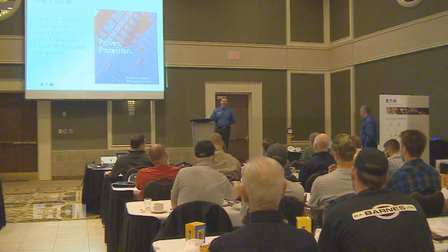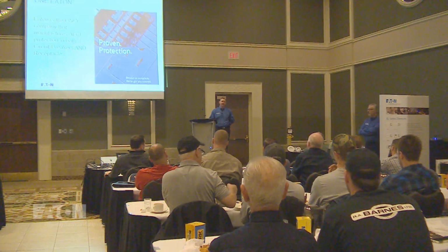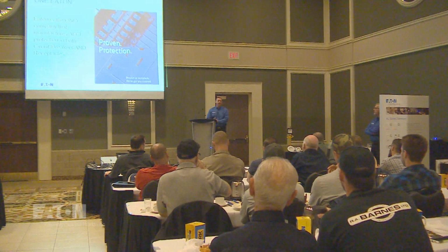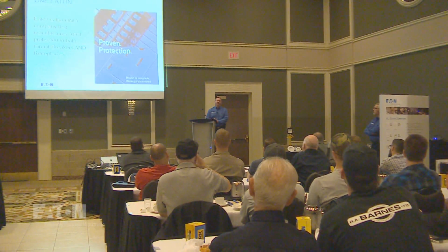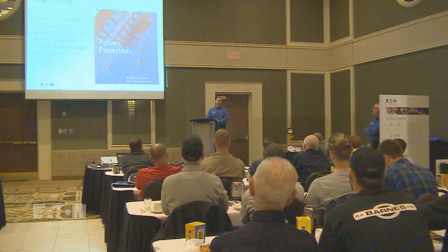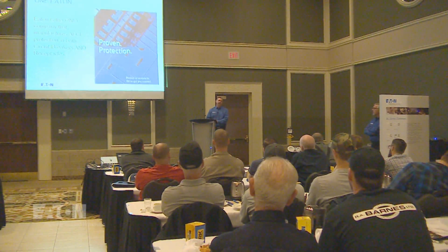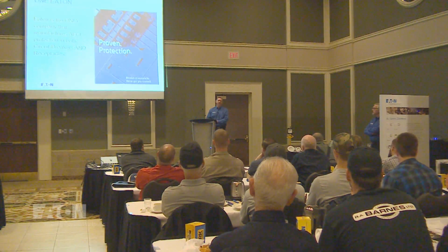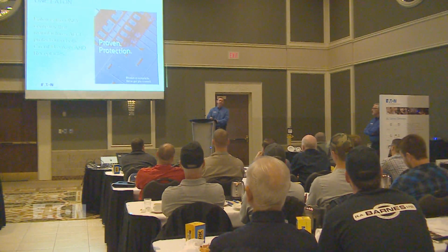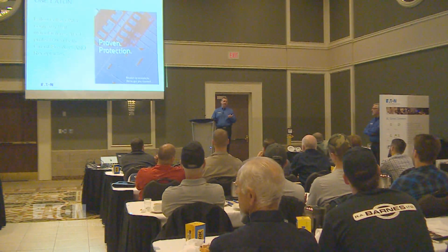The comment was, if there is a problem in the circuit, it may be impossible to troubleshoot what the actual cause is. That's a good question, because the AFCI technology we're implementing at Eaton has a diagnostic LED built into the breaker that'll give you either 6 trip codes or 7 on the CH line, because one of our products has some ground fault testing greater than 30 milliamps, so not people protection, but it actually looks for ground faults as well. So it'll actually give you the reason it tripped, right? So now you know the branch circuit that it tripped on, right?